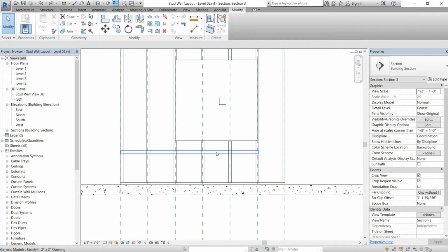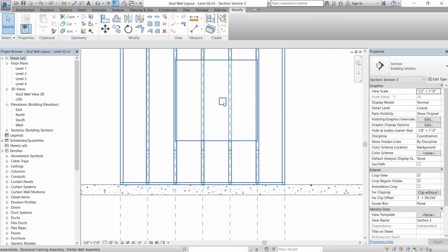I'm going to do another video where I show how you can use these with model elements. Like I said before, with a shelf, if you want to add a shelf with an opening on it, you just put the shelf in, and then just say cut elements that are in the way of the shelf, and it'll give you a tolerance around. So let's say you need 10 millimeters around the whole shelf as an opening. You can set it up that way too.